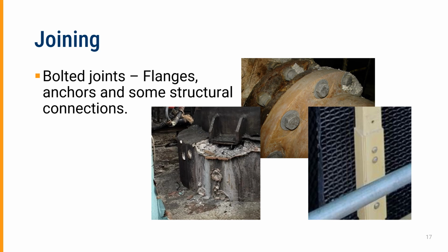Also for joining, you can use bolted joints. Flanges and anchors and some structural connections use bolted joints. These require a little bit more design finesse because you end up with off-axis loading and bending moments that you have to contend with.